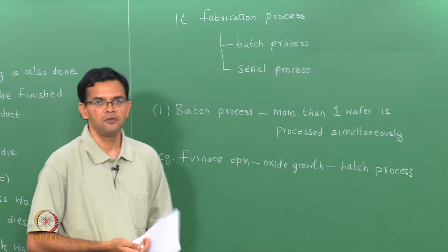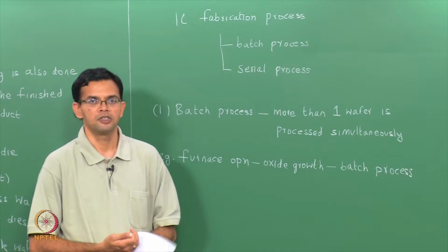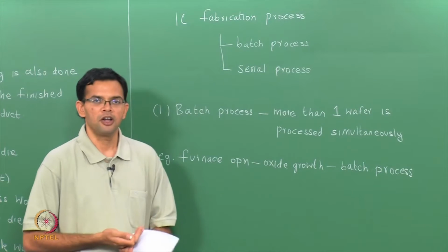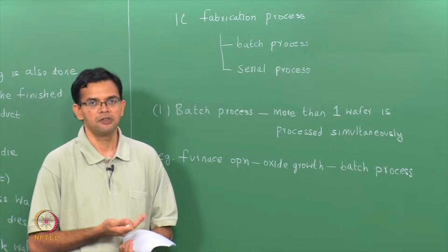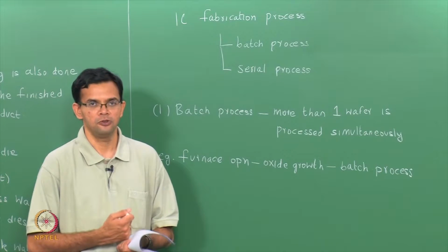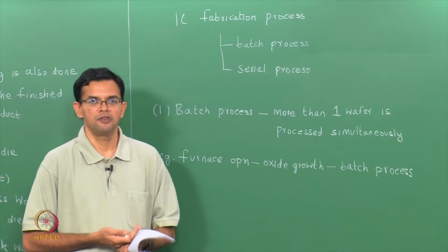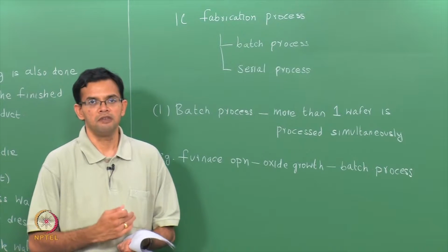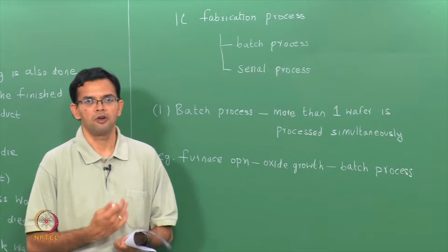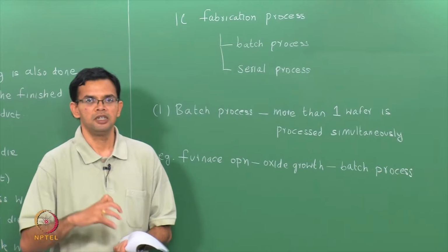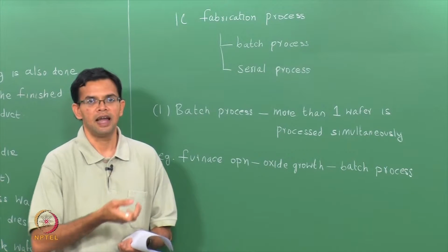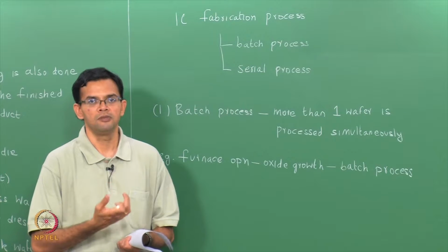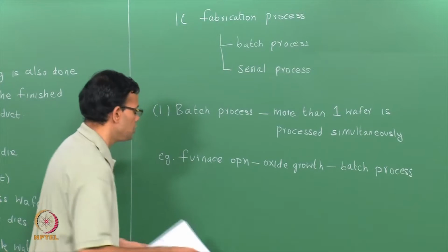Not all of these wafers are product wafers. So, along with the product wafers, some blank wafers or test wafers are also used, and these test wafers can then be evaluated. Because they receive the same treatment as that of the product wafers, by measuring the test wafers we can get an idea of how the film was grown on the product wafers.